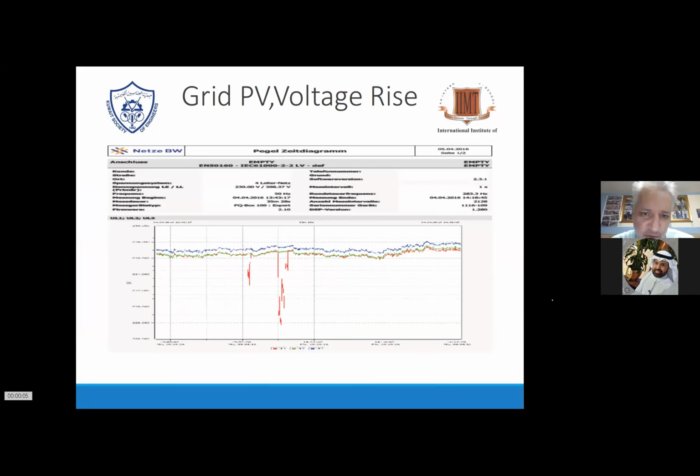That's the Siemens inverter, like I showed you. The problem at that time was that the people doing the checkups were checking the medium voltage side, and when you check the medium voltage side, you check transformers only. At least that's what the Germans did. That means 15-minute intervals. Of course you never will pick up any errors, because the buffer of 15 minutes is way too far. So I had to put the intervals down to 1 second.